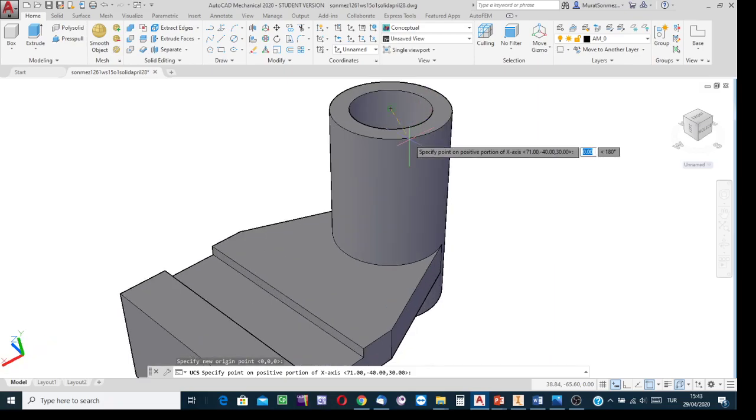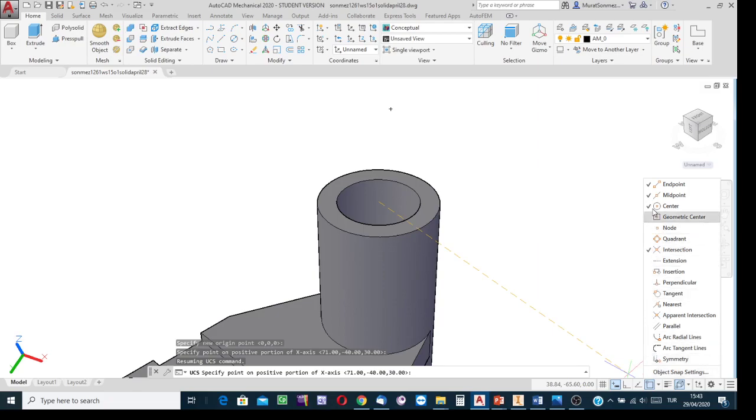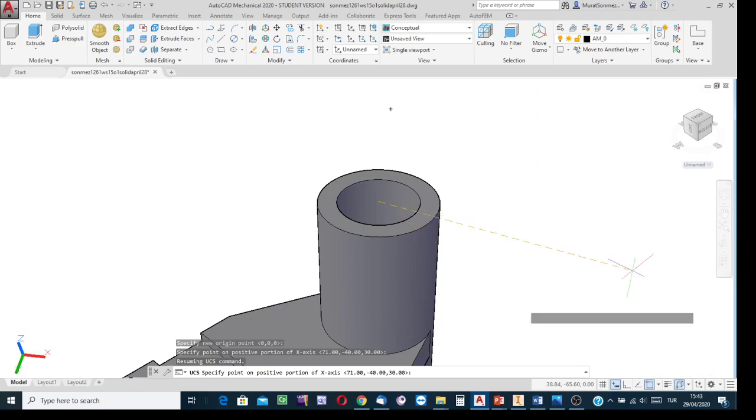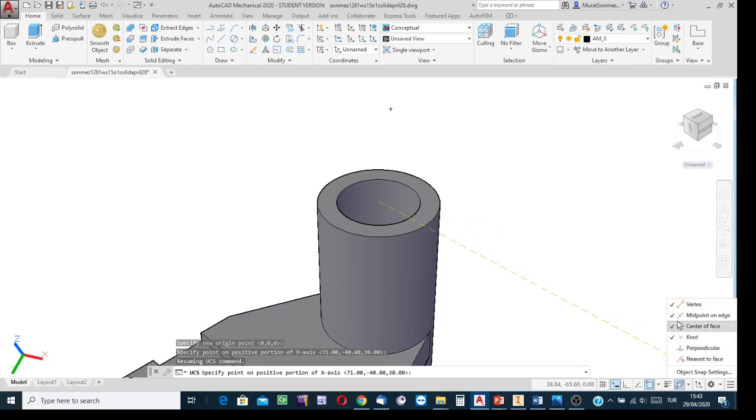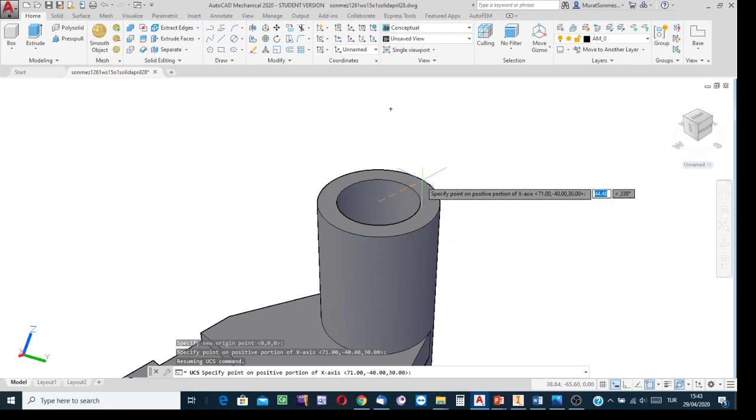But you see, although with snap enabled, sure, for midpoints there is an enabling, and also 3D snapping, for midpoint on edges there is an enabling. But when I bring the cursor to this part, you see, although by definition there is a midpoint of this part of the circle, the midpoint is not highlighted, so the midpoint cannot snap the cursor, so I cannot indicate the midpoint.